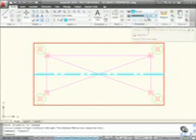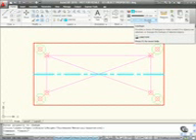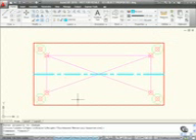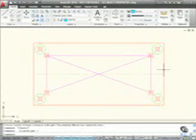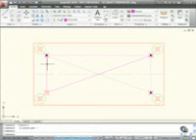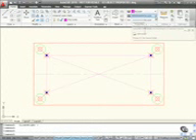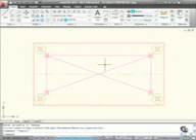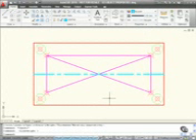So always make sure that when you click on these, that you're using the right one. Line type, line weight, color. You'll see the mistake that I deliberately made there. It didn't change its line weight because I clicked on here and then went up to here, but I didn't actually select 0.35. So as you can see, that's now standing out. If I switch line weight off, they adopt the default line weight. That's purely for clarity so that I can see what I'm drafting. If I apply this one and this one with a line weight now of 0.35, they don't actually look any different at all because line weight isn't on down here on the status bar. Now it's obvious that we're using a line weight.